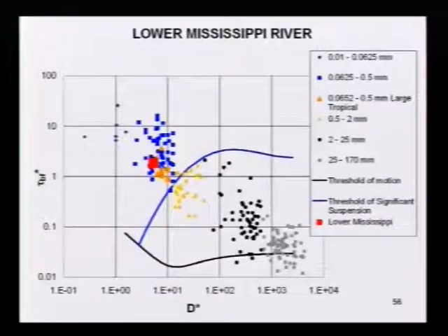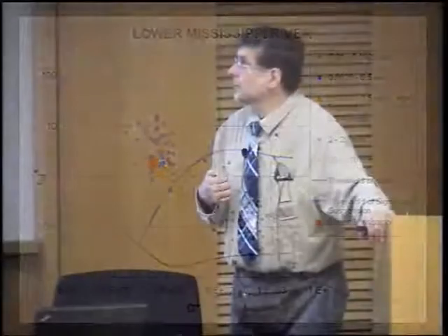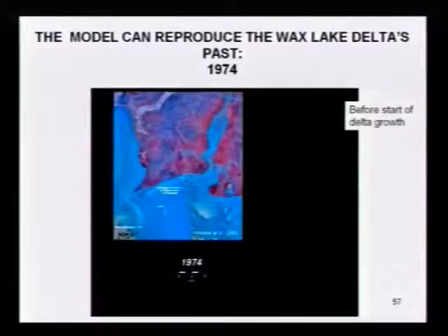Where do we fit in the scheme of things? That is the values of grain size, dimensionless grain size, and Bankfull Shields number that we used to model designed avulsions or diversions of the Mississippi River to build land. Now, again, I'm not going to go into the details of the model, but it's classic morphodynamics. We link hydraulics, including shallow water equations in axisymmetric coordinates, and a sediment transport relation, in this case the Engelund-Hansen relationship, which is appropriate for a large sandbed, for sandbed rivers in general.